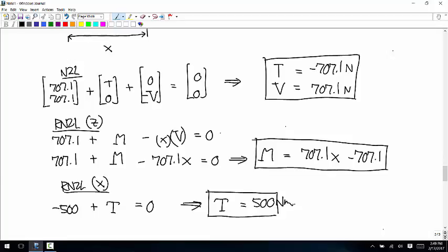So based on this function, if the possible x values are between 0 and 1, where do we have the biggest absolute value of the bending moment? At 0. So what that says is right at the wall, material points right near the wall are the points where we're most concerned about this beam being broken by bending. And then that value becomes a smaller and smaller negative number as you get closer towards the end.